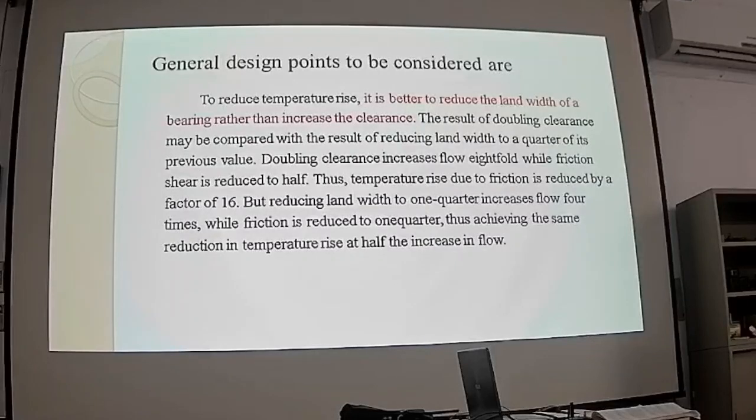But the strategy is that first you need to reduce the land length rather than increase the clearance. Because if you increase the clearance, the thickness of the oil film will increase and the stiffness will decrease. So therefore, you should select the first strategy, just reduce the land length ratio, and reduce the land length.